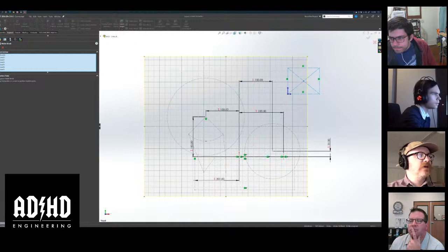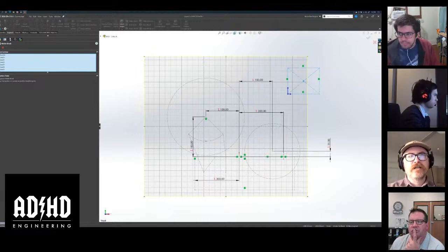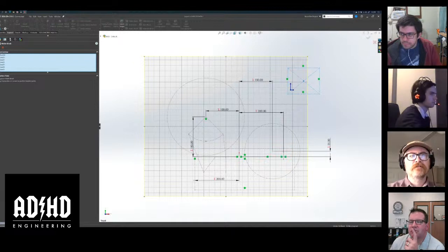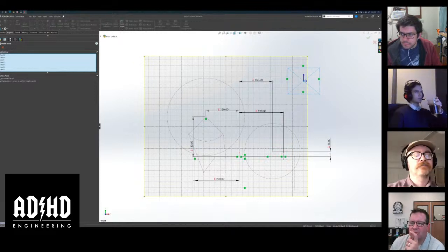Now, to be honest with you, I don't know what layout sketch block does. It doesn't seem to do anything useful for me, so I just don't use it. All I do is click insertion point, and then this shows up, but I don't pay attention to what that is. And you notice this origin showed up. I don't really find any of these corners useful, so I'll just take it and move it, and it'll snap just like that. So now it's snapped to the center of the square, and I'm not done making the block, but it's okay because I haven't actually dimensioned it or anything.